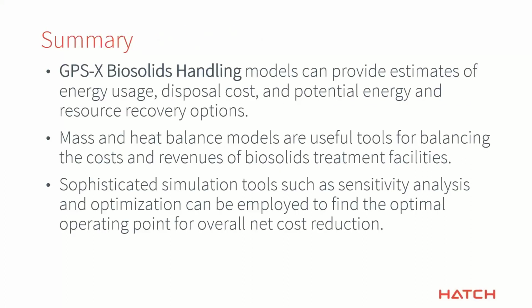Okay, so just to wind things up, as we're getting a little bit out of time here, the GPS-X Biosolids Handling section, those models can provide estimates not only of the performance of the treatment, but also how much energy was used, what the disposal costs will be with whatever's left over, and the potential energy and resource recovery options.